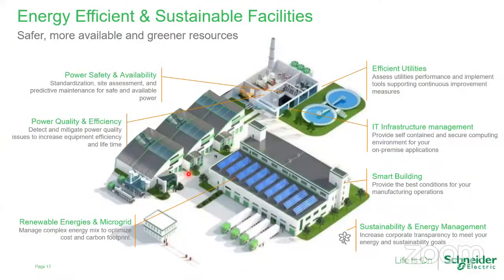Now these are the various things you require. For example, if you want to make your college or your university energy efficient and sustainable, how can you plan? There are a few angles here. First, you should look at your utilities. Utilities are basically your air conditioning system or your water system, which is required for your college. You should see how to make it more efficient. We need to monitor the performance of water consumption, power consumption, and air conditioning systems, with complete parameters like temperature, chilled water flow, and power consumption. Everything has to be monitored.